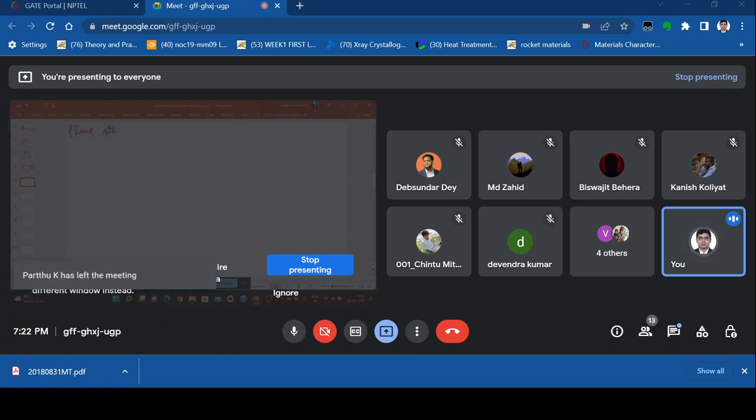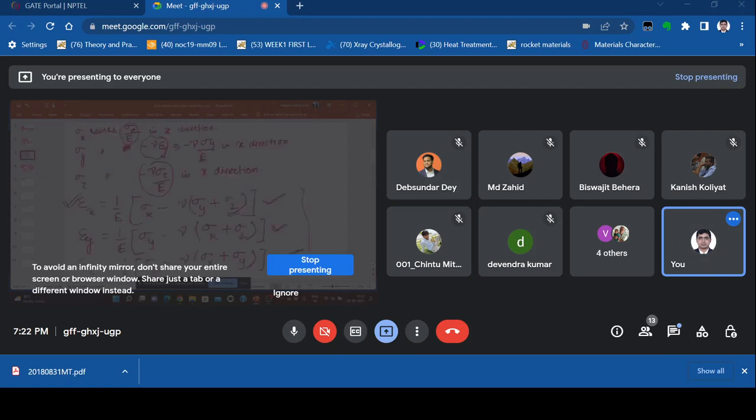Now let's consider plane strain condition. So here, as before, we put sigma z equal to 0 or sigma 3 equal to 0. Here you have to put epsilon 3 equal to 0 in the same equation. Okay, just put this equal to 0 here only. Sigma z everywhere, put sigma z equal to 0. Basically, these two, epsilon x and epsilon y, will be the same.